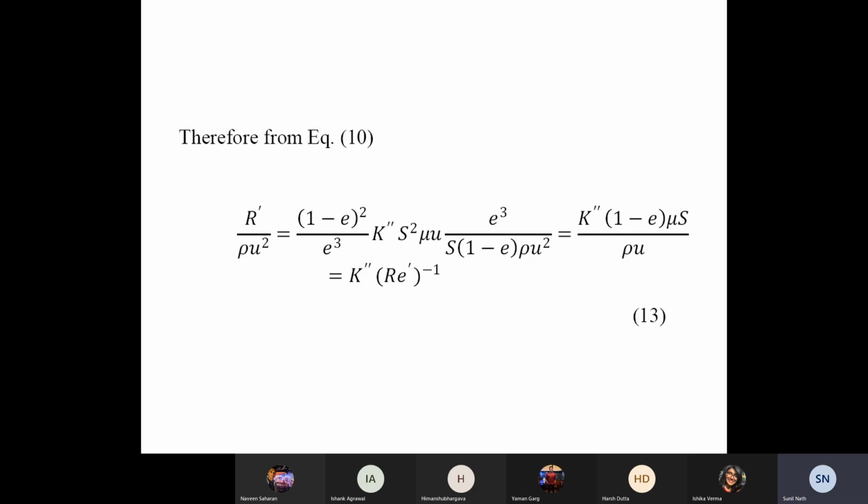So this equation is applicable for values of the modified Reynolds number less than about 1, that is under streamline flow. Now what happens at higher RE values? Slowly in the largest channels, because the void fraction is not always controllable, the flow starts to slowly go away from streamline flow and drift towards intermediate and turbulent flow.